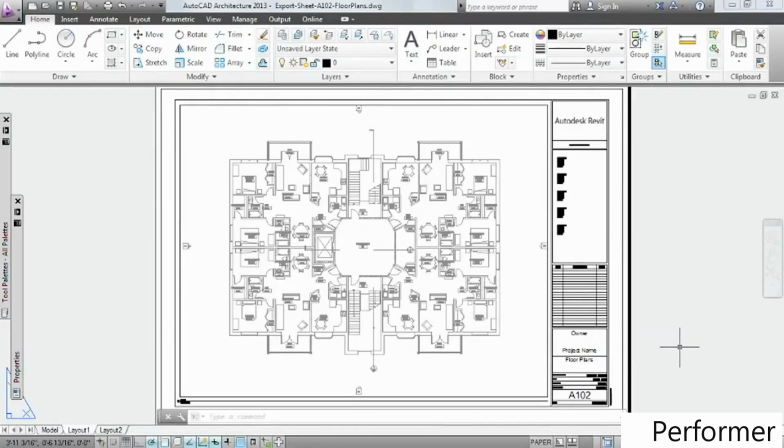It takes a little bit of setup, but once it's set up, it's a fairly straightforward affair. You can take all of your Revit views, export them out, and they become separate DWG files complete with title blocks, paper space, and XREF views. It's very handy, and the recipients on the AutoCAD side will appreciate the setup because it will match the office standards.